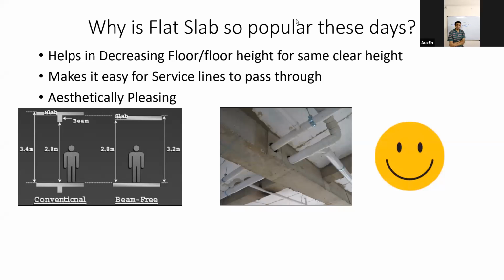Now this is not a very good solution for a number of reasons. One reason is that you are cutting your concrete from there. In the places where you have high shear zones, cutting concrete from the high shear zones does not make good design sense. Also, when you are reducing the concrete, you are reducing the compression area of your flexural member. So again, your flexural stresses are disrupted.